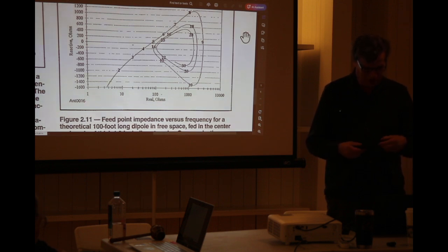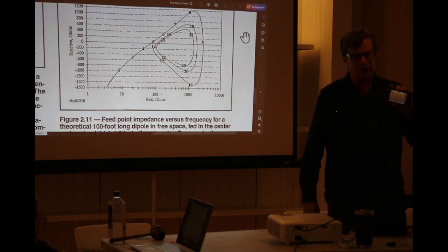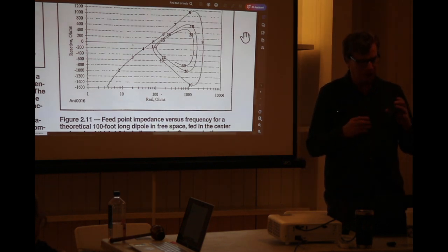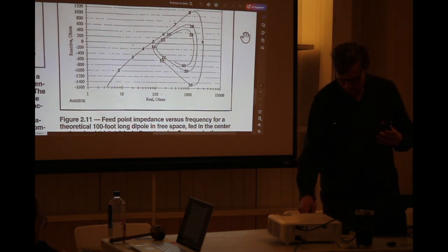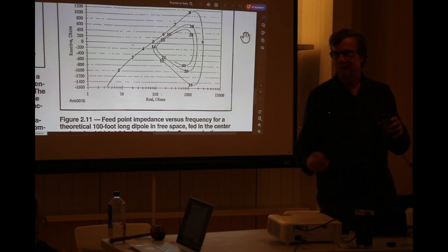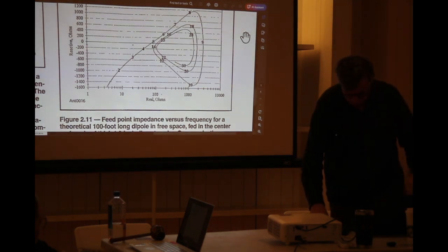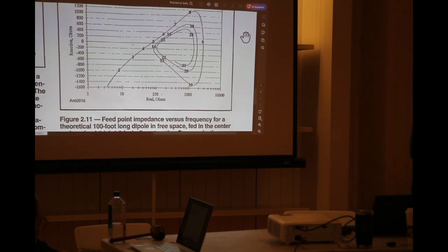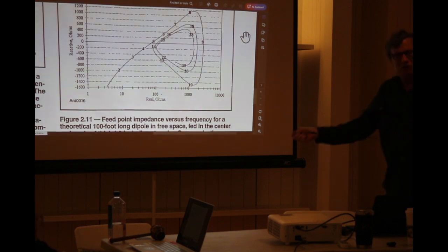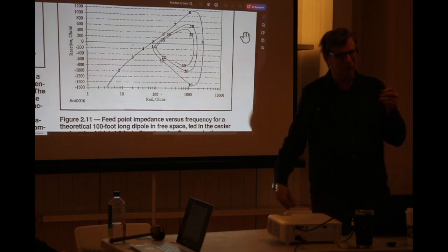So, you have VNA, and your standard 3-point calibration, which I recommend, is you first go to calibrate mode, and then you put an open circuit and then a short circuit and load. Most of the time, unless you're going to be right at the antenna, I like doing the 3-point calibration with whatever cable I'm using. And the reason for that is, if you do this right, it doesn't matter what your length is. The whole point of 3-point calibration is to calibrate out your transmission line.